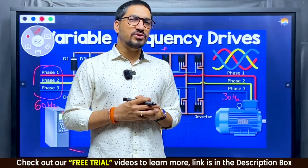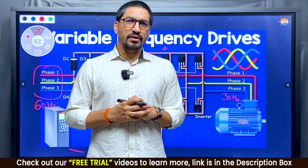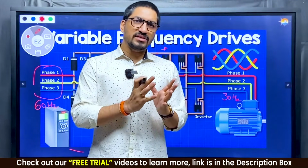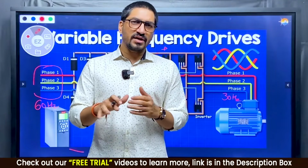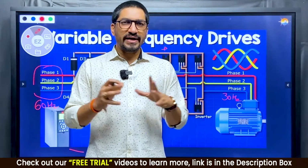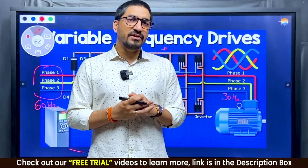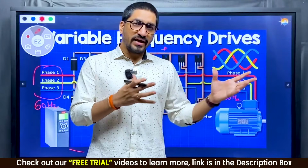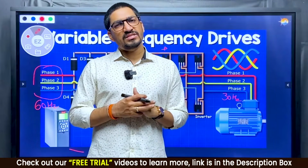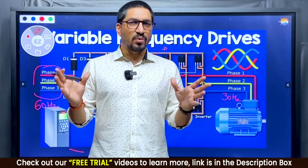These days, gentlemen, there is too much talk about energy saving. So we are now developing more and more such systems on board ship. When the flow rate is not required, you can reduce the speed of these motors. For example, engine room blowers. When the ship is in port, you don't need too much airflow into the engine room, which earlier, when the engine was running, was needed for burning the fuel, so air would be sucked in by the turbocharger. Since you are in port, the main engine is not running, so the requirement is less. So you can reduce the speed of the blowers.